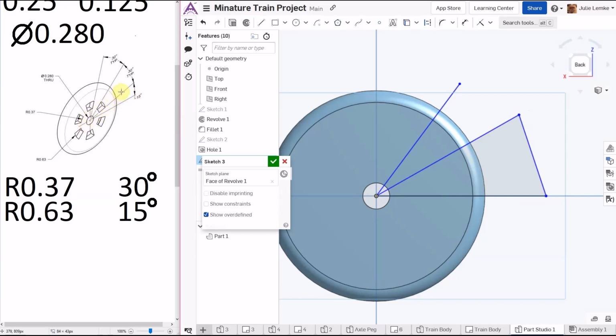And then I added these two lines right here for the sides of the window that I'm going to cut out. The next thing I'm going to do is use my center point arc, put in the center, and connect those two, and then do it again. Okay. All right, so now we can start trimming.